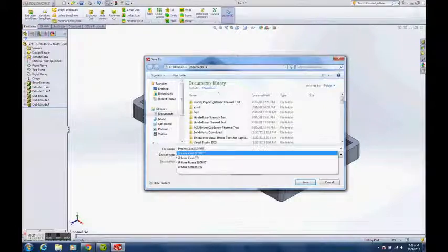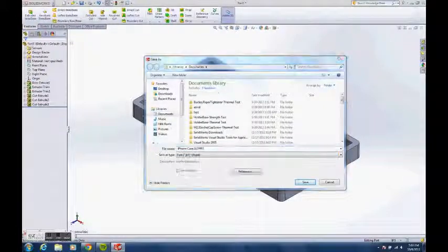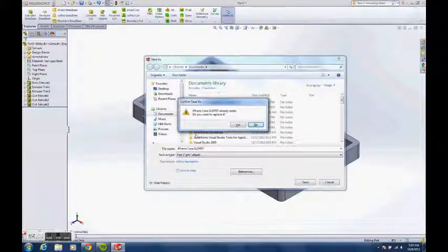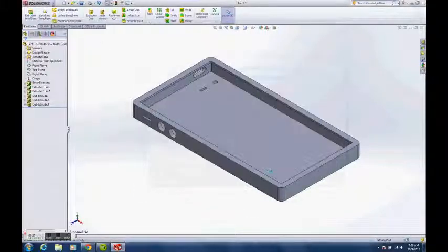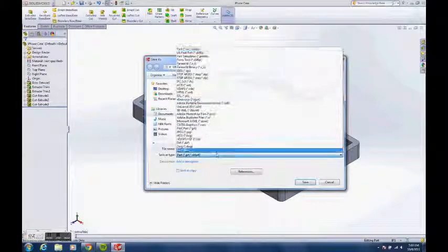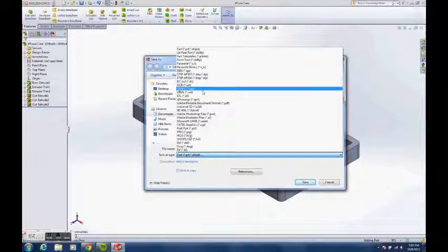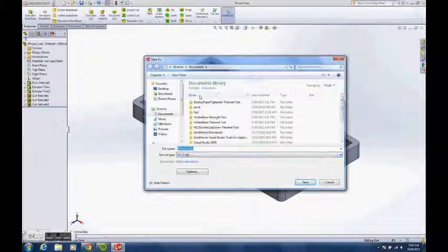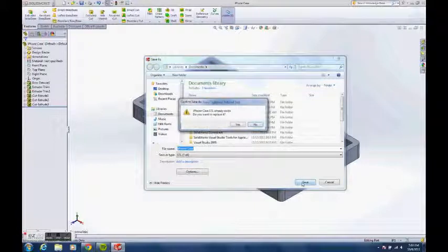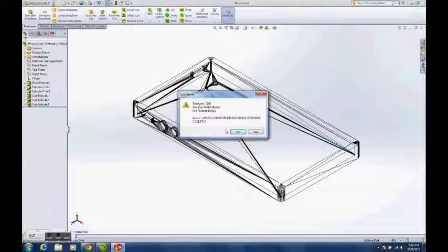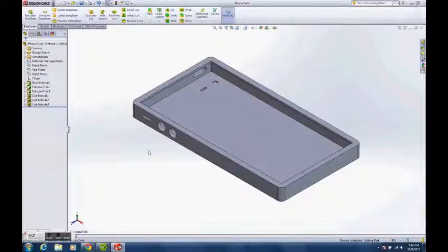An important point to be made about modeling for a 3D printer is that you want to make sure that your model has a base that is mostly supported by itself, or else you'll spend a lot of money in support structure material that the 3D printer will create so that your part doesn't fall apart while it's being 3D printed.